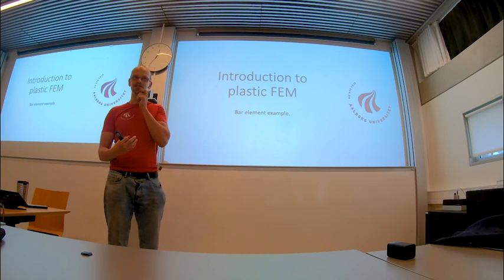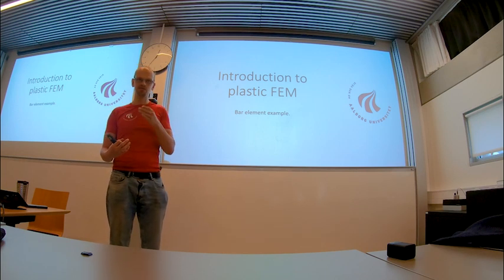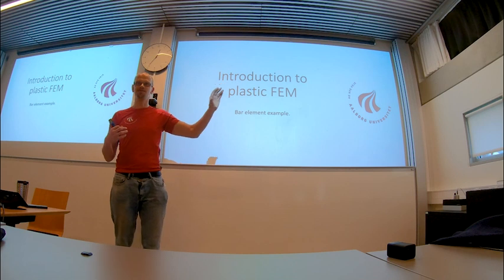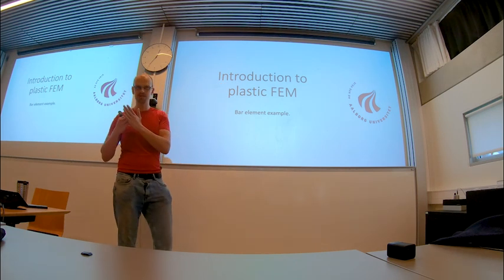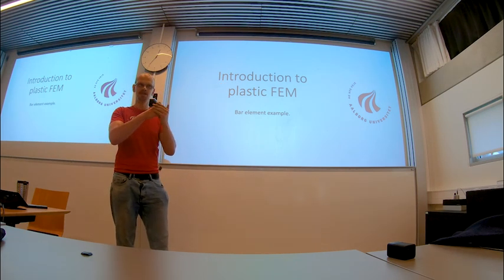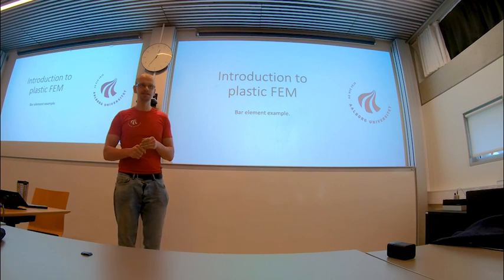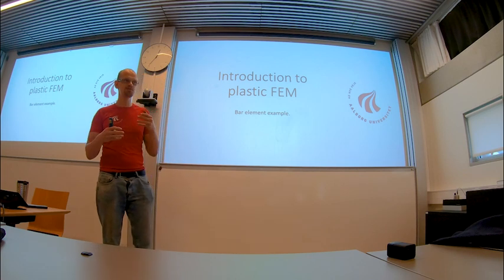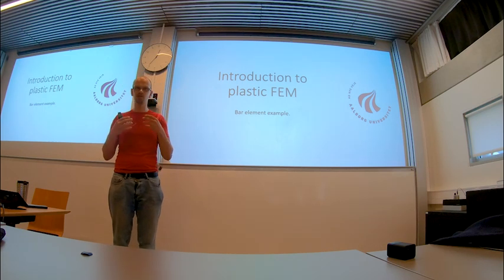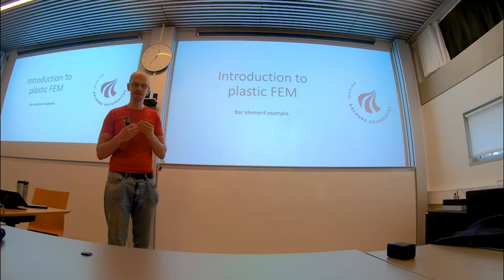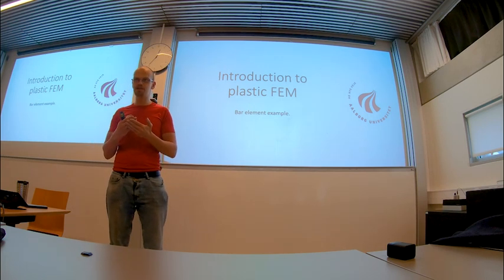So one approach is to say, we apply this force, and at the point where it fails to solve it, that's the maximum. Another approach is to keep applying more and more deformation, and then you record this curve. And I want you to be aware of both loading options very consciously, kind of understand the difference, because it also happens in the real world.